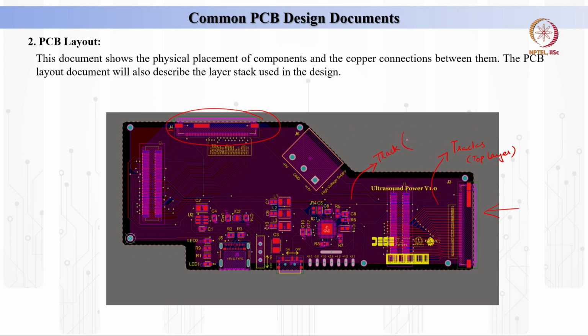So this is actually a 2-layered PCB. Since the number of components is very small, I have used a 2-layer PCB, and you can see all the components populated here. All the components colored with light blue are multi-layered or through hole components, which means there is a hole through and through, there is no physical PCB present there.